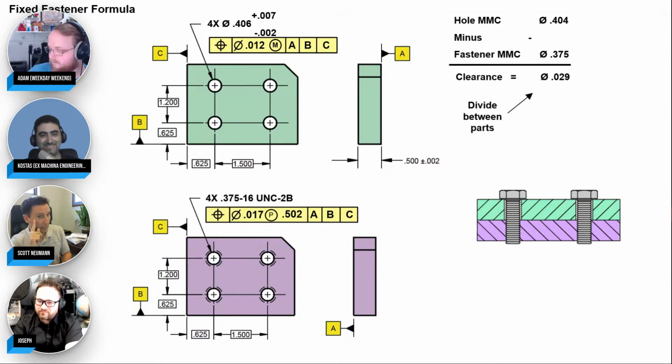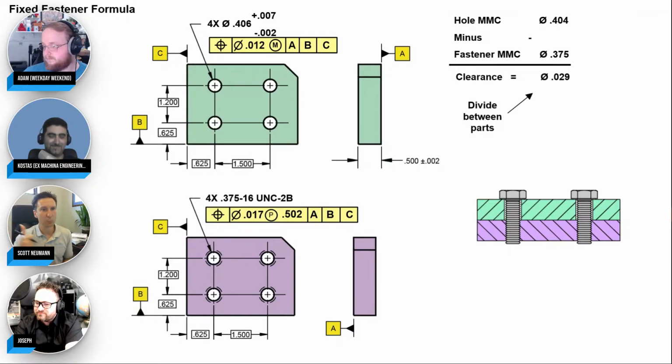Now, a good quality engineer is going to look at that and say, ooh, I see you want 17 on the pitch, but I want to make a cheap gauge on the minor diameter. So I'm going to artificially guard band the tolerance myself. That's what I recommend quality do. You guard band artificially. So, all right, we're going to use a gauge for this. We're going to bump it down to 15 thou and go off the minor diameter. And we still think we met your function. Cool. You do your thing.